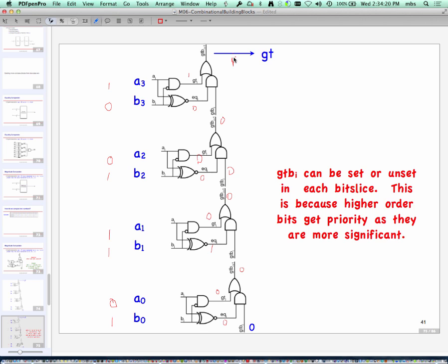So is that thing over there considered a NOR right now? If it's a NOT in front of an XOR, is that considered a NOR? No. Like the gate. What is that considered? You're referring to just this part? Yeah, with the NOT in front. It's called XNOR. And this little gate on top of it with a bubble has no name. It's an AND gate with an inverter at one of the inputs. There's no standard name for it.